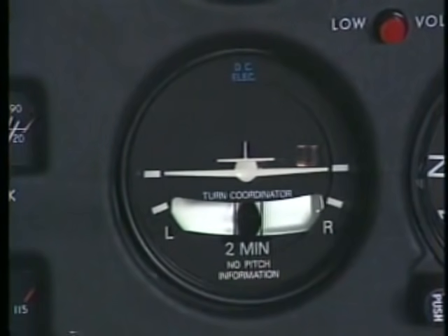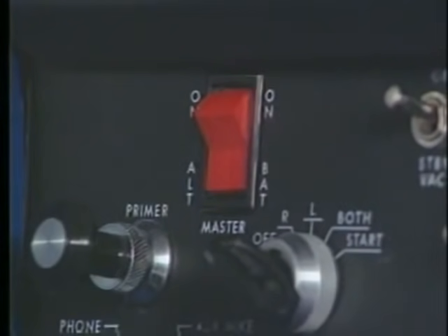Once inside the airplane, check that the wings are level in the turn coordinator, that there is fluid in the inclinometer, and that the ball rests in the lowest point. Then when you turn the master switch on, listen to the sound of the electrically driven gyros and make sure there are no abnormal noises.